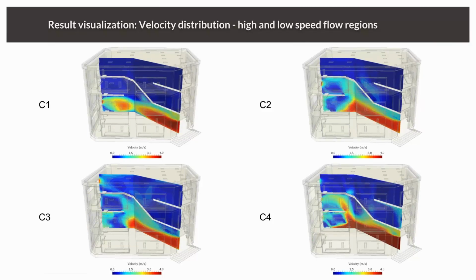And we can also create slices in another direction. This is basically now a slice which is following the stairway. And here you can see again that the big draft is directly coming in through the entrance door, and we have some recirculation here. Especially if only the windows on the ground floor are opened, this creates a strong draft because it's directly going through the room.